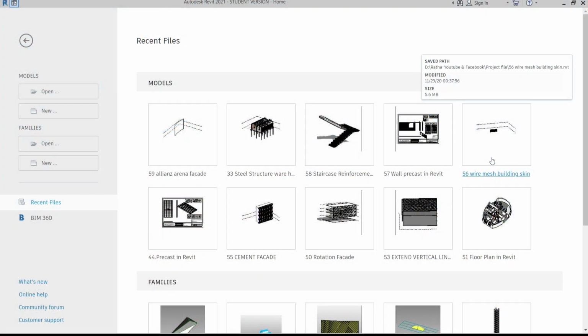Okay, as you can see, I'm in Autodesk Revit 2021 student version. In my case, I would like to create those components first. I go to the conceptual stage to create these steps before applying them into our project. You can use two ways to create that: first, a generic model pattern-based family, and secondly, an adaptive component. I prefer the generic model pattern-based family because my style is that I always want exact sizes when I apply patterns or adaptive components in my project to improve my design.